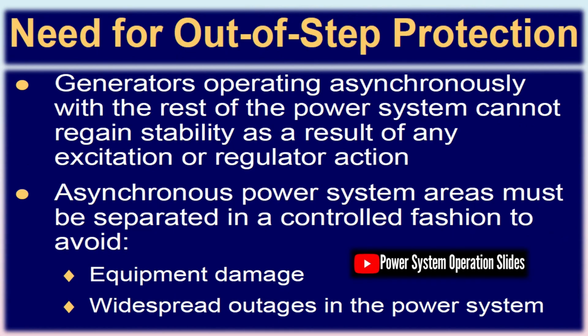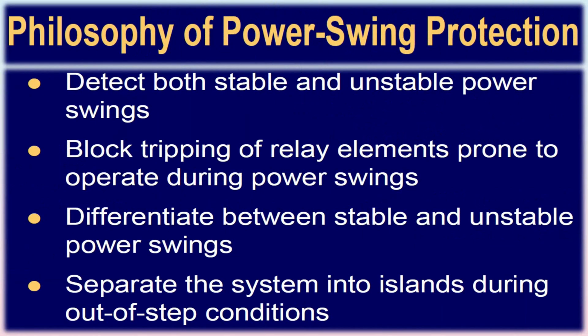The power angle curve is a fundamental tool for visualizing and understanding generator behavior. It plots the active power delivered by a generator against the load angle, the phase difference between the generator's internal voltage and the terminal voltage or that of the grid. Key aspects include sinusoidal nature: as the angle increases from 0 degrees to 90 degrees, power transferred rises, reaching its maximum at about 90 degrees.